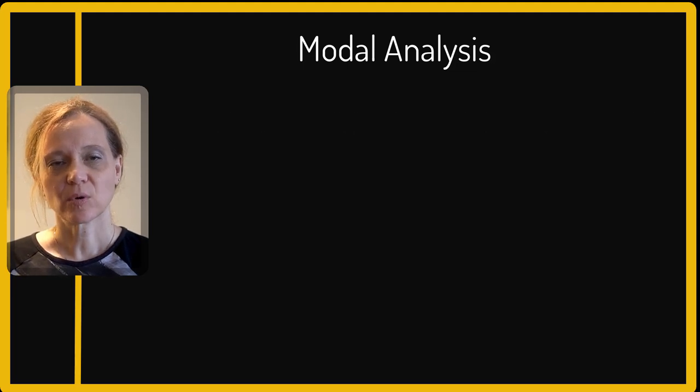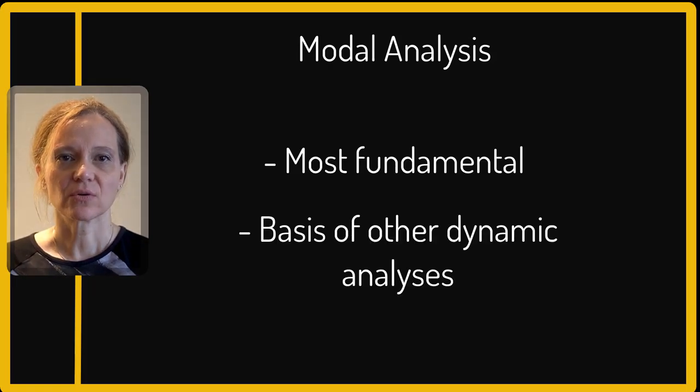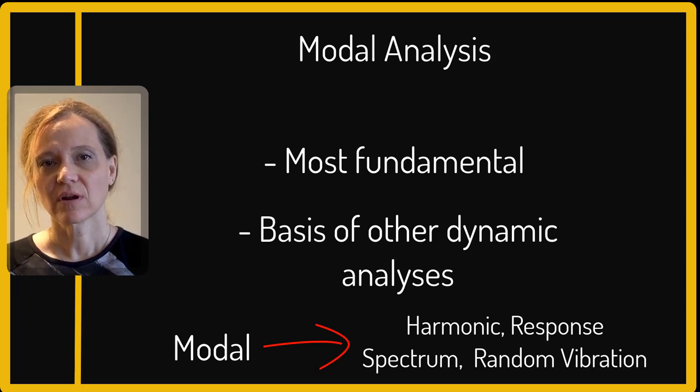That is why modal analysis is the most fundamental of all dynamic analyses. It is the basis of all other linear dynamics analyses, such as harmonic, response spectrum, or random vibration. Let's see how we can calculate natural frequencies and mode shapes.